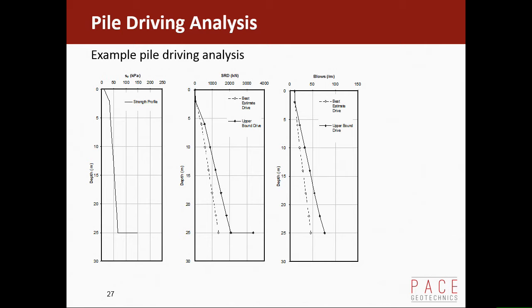And the cost can be quite significant, because I've been involved in one case where the pile, I think it was oversized, but they had an analysis done by somebody who came up with a big hammer, unrealistically big, but that had an impact on the crane. They couldn't use the crane, they had to get another boat with a different crane to lift the hammer, and if you'd selected the right hammer in the first place, it would have been a lot more cost effective. But because somebody had said it might be this size hammer that you really need, they grossly over designed the pile hammer, and everybody was frightened to go away from that because, oh, what if it doesn't drive? It was really a lack of competence from the original site investigation contractor.